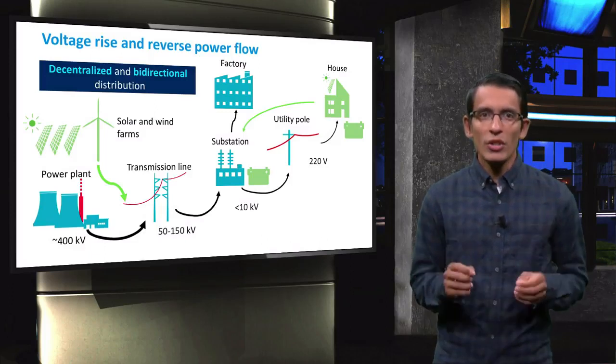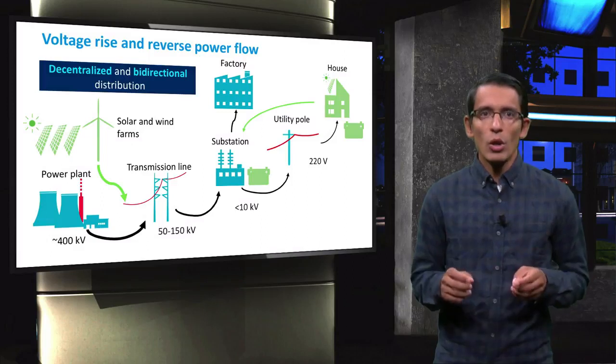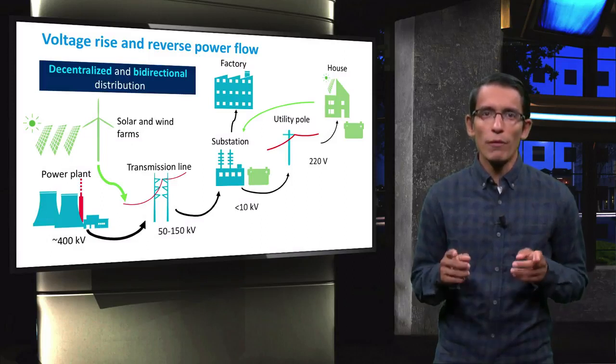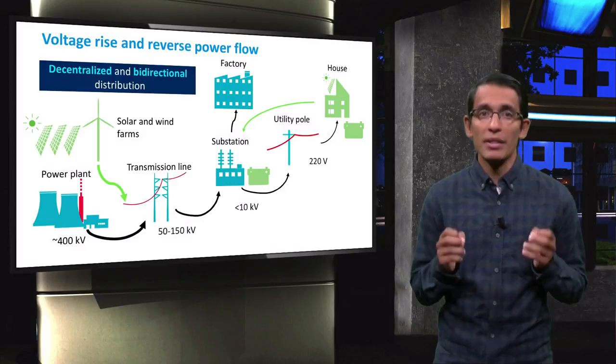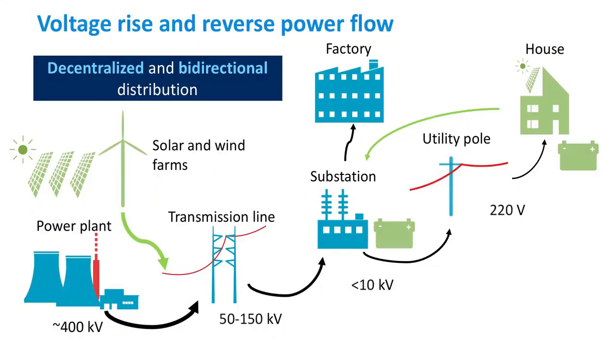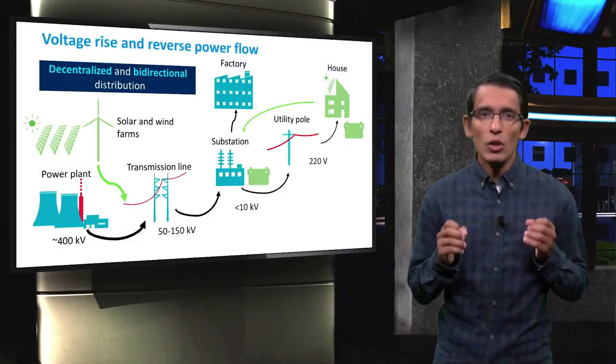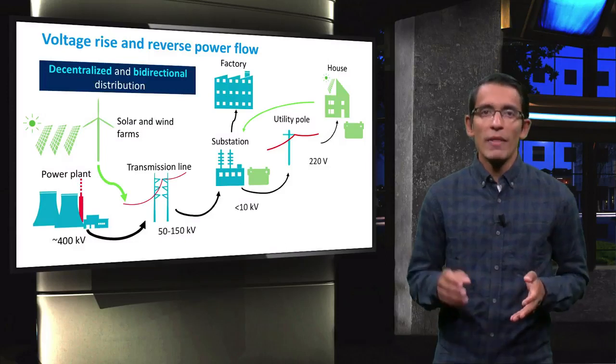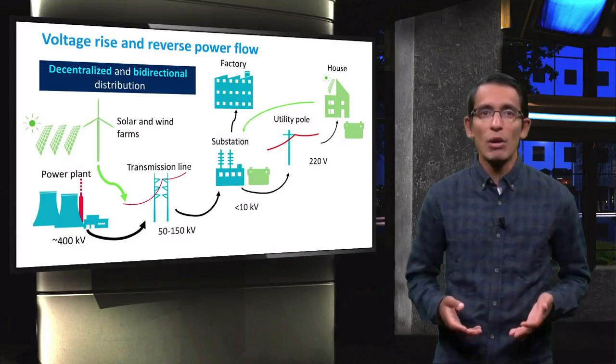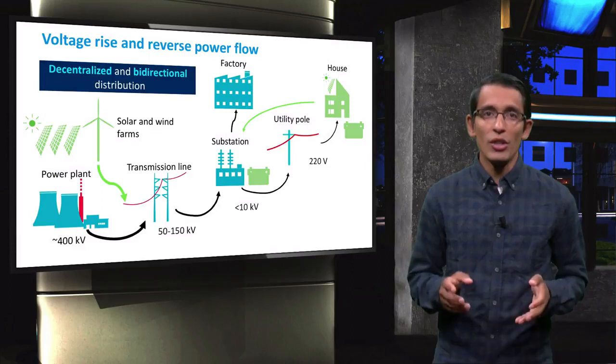If distributed generation systems result in a reverse power flow through the regulator, tap changing control systems in the transformer, which regulate the turn ratio and therefore the voltage inputs and outputs, may become unstable. Distributed generation reduces grid reliability if care is not taken in the design of tap changing to handle downstream and upstream current flows. This is the biggest challenge when designing new electricity grids like smart grids that can guarantee control over complex power flows given by distributed generation such as PV.